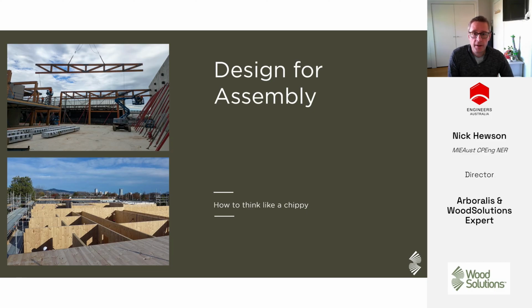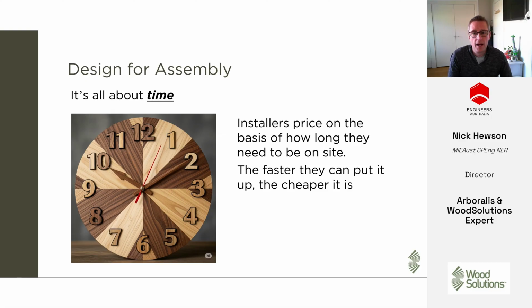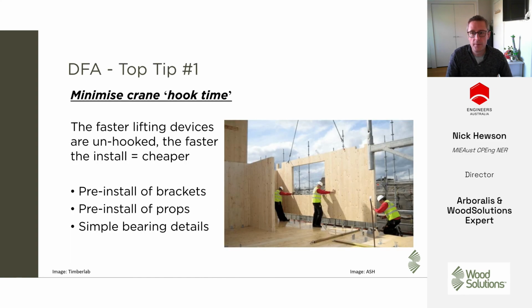So I'm going to talk about design for assembly now, or how to think like a chippy. The big thing here to bear in mind is it's about time. Installers will price on the basis of how long they need to be on site. That's not only labour, but it's also hire of scaffolds, cranes, the likes of propping. The faster they can get done, the cheaper the cost is. So you've always got to bear that in mind when you're thinking about design for assembly.